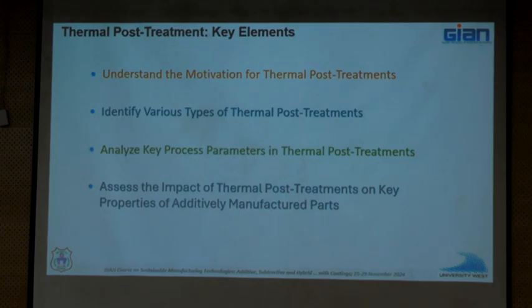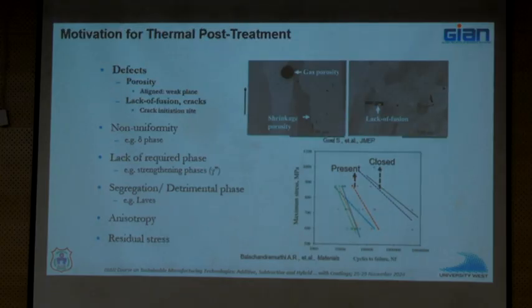What happens if you post treat at a very high temperature? When does grain coarsening begin to happen? You don't want that. And then assess the impact of these post treatments, especially on mechanical properties, because more often than not, that is the driver for thermal post treatment. Functional performance, not surface attributes, right? So, we will talk about that.